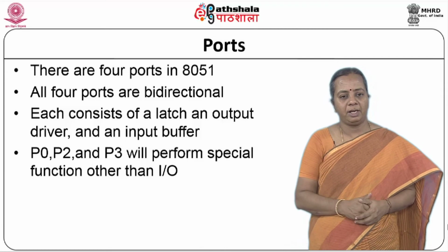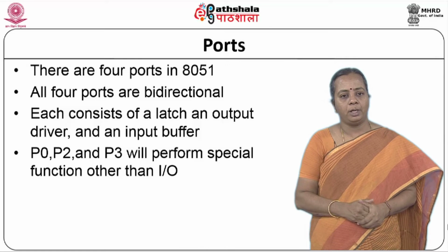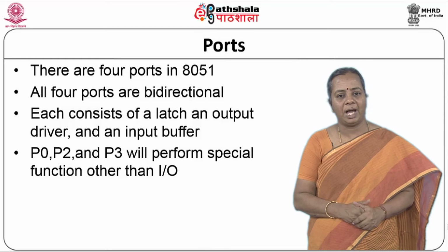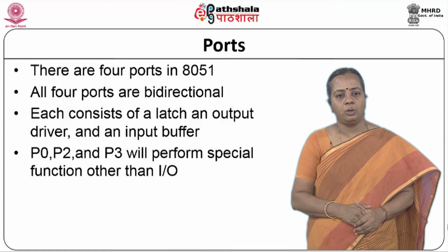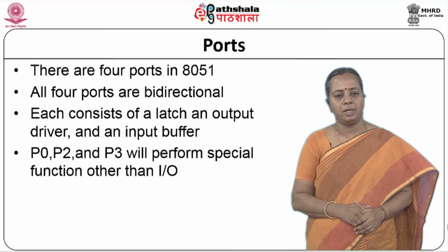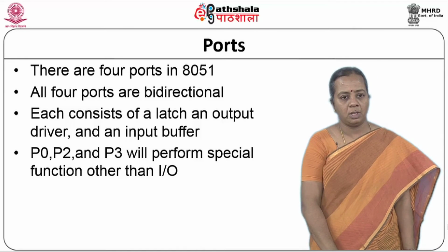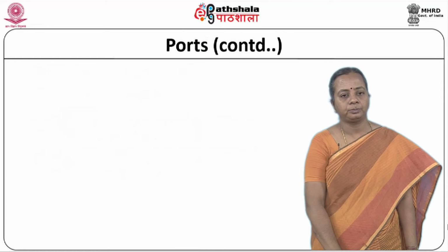You can read the data from outside, or you can send the data to outside also. So, when you are having a latch, these ports will have a latch and there will be an input buffer. When you are using a latch, maybe you will be sending data outside, and when you want to read something, the input buffer is used. P0 and P2 are used, and your P3 will perform special functions also.